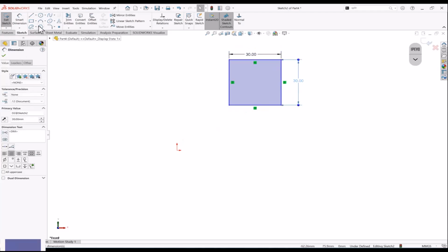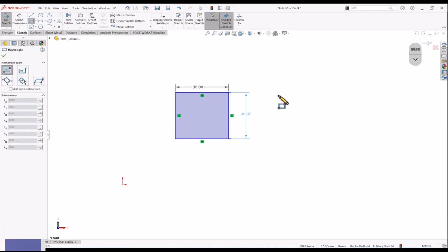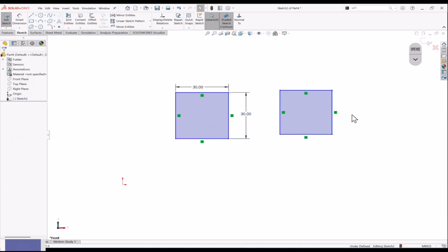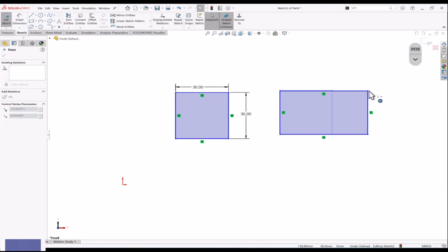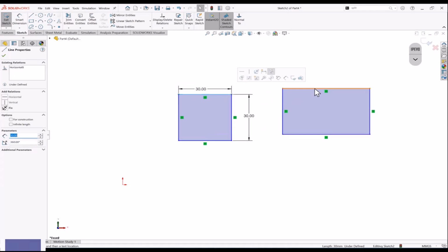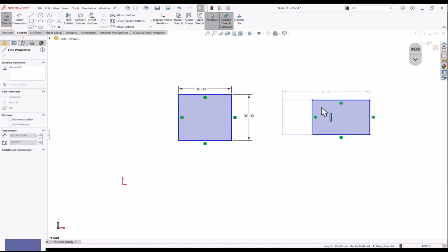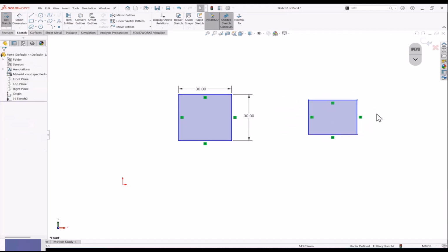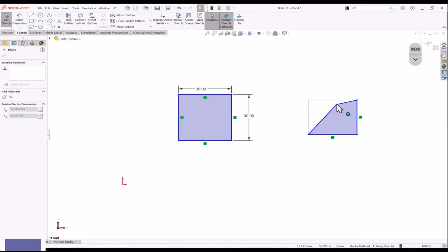If I make a normal sketch, let me explain something more. So if it is a normal sketch, what happens? If dimension is not there, what will happen? You see, this will vary. If dimension is there, what happens? It is moving in different directions. Means size is not varying, but the object moves. But here, the object will also move and the size will also vary. And this is called geometrical. This you see, horizontal vertical relation, it's called geometrical relation. If it is not there, what will happen? See, this will happen. The shape will not remain constant.